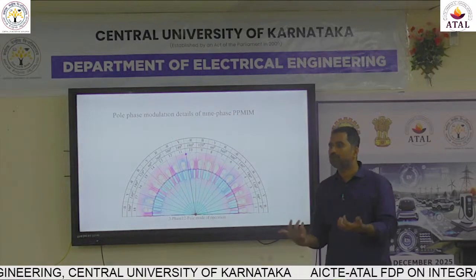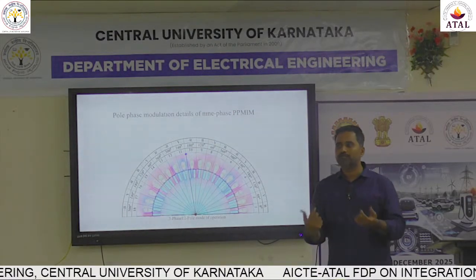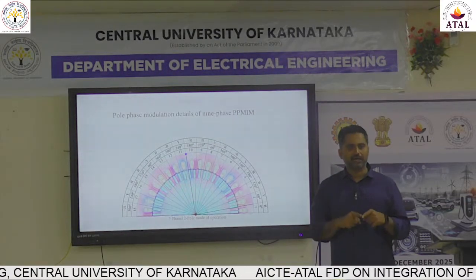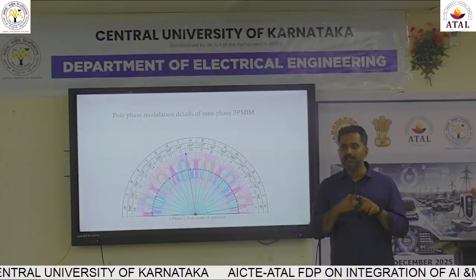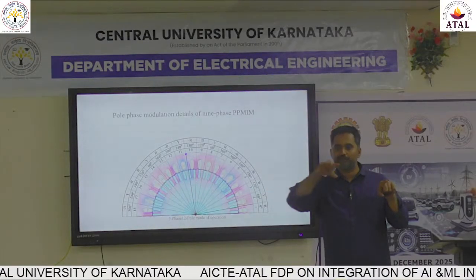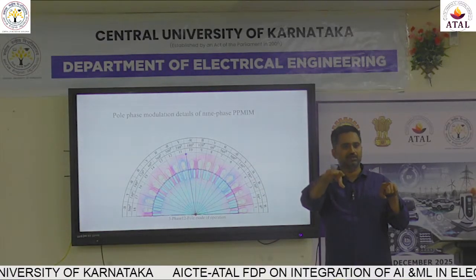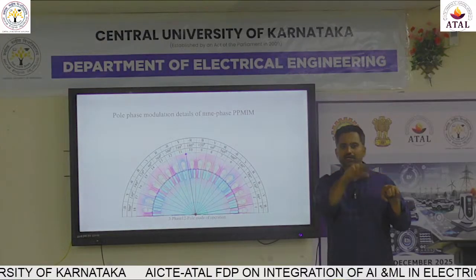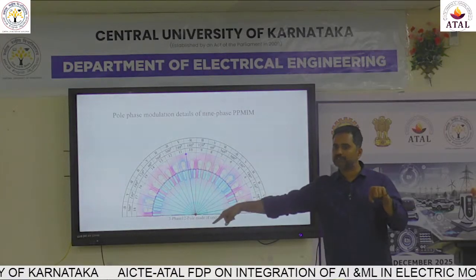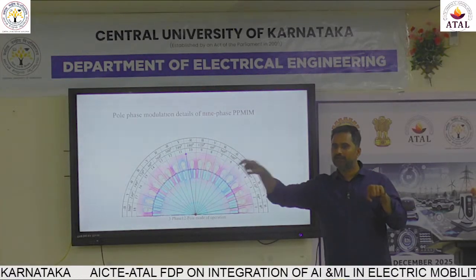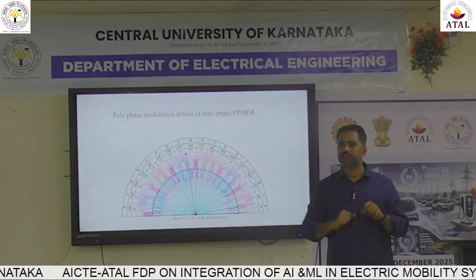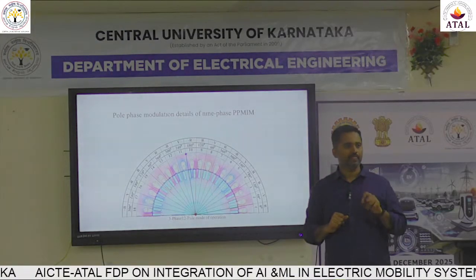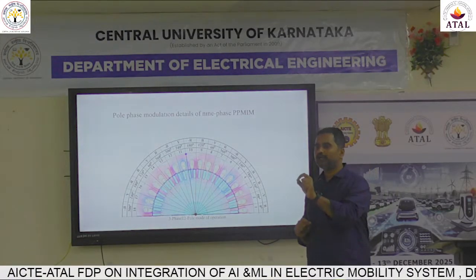You may say, why should I worry about it? If you don't worry about leakage inductance balancing, the current mainly depends on the supplied voltage minus back EMF divided by the leakage inductance and resistance only. If this leakage inductance is not balanced, even with the same voltage, because the speed is the same and the back EMF is the same, the currents in each phase can change. Why is this important?